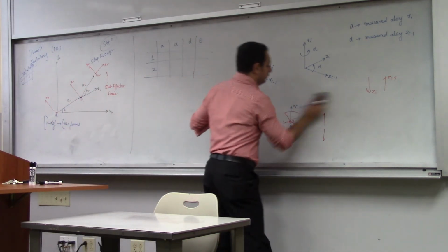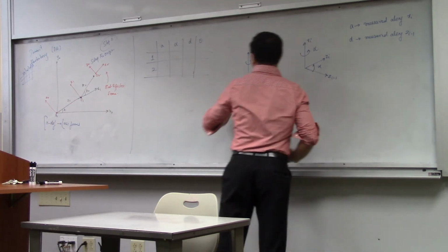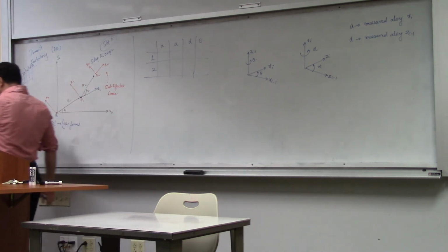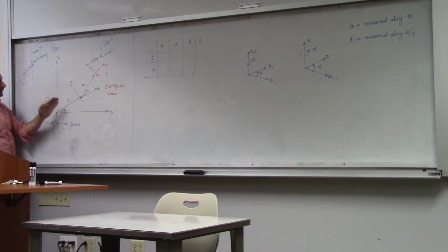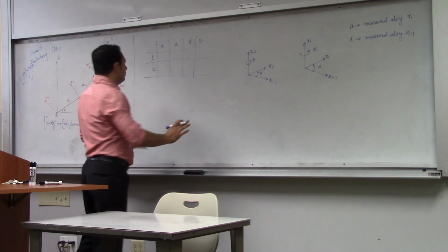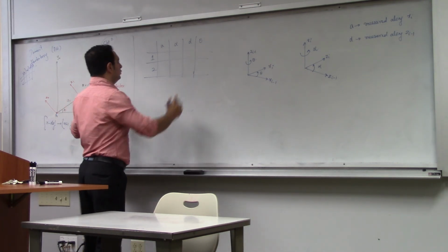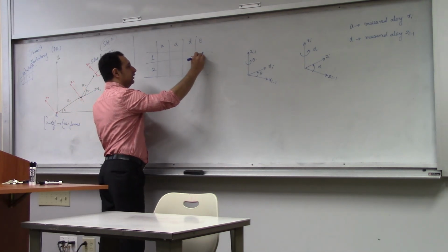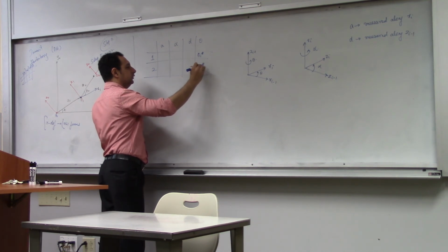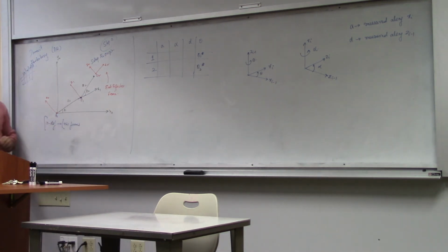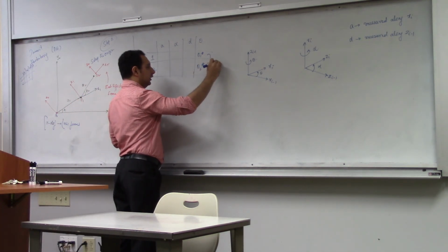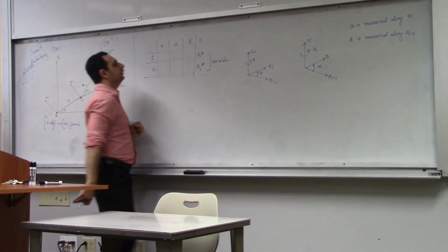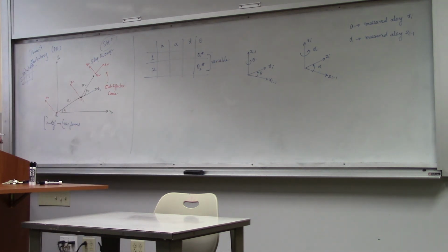But until now, the first thing is setting up the frames. We start with setting up the Z, which is very easy, perpendicular to the axis of rotation or along the axis. Locate the origin, set up the x-axis. Now, because these are two revolute joints, we'll write this as θ1 because we know this is going to be variable. These two are variable parameters, so I'm just going to put them as asterisks. Everything else in this table is going to be constant.